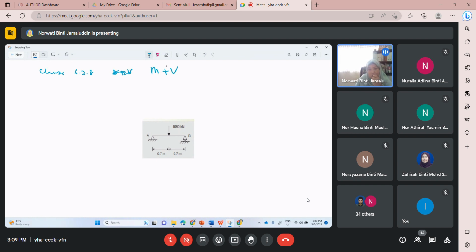So to clarify whether it is low shear force or high shear force, it said that VED is compared with 0.5 VplRd. We have this value because we already calculated that.